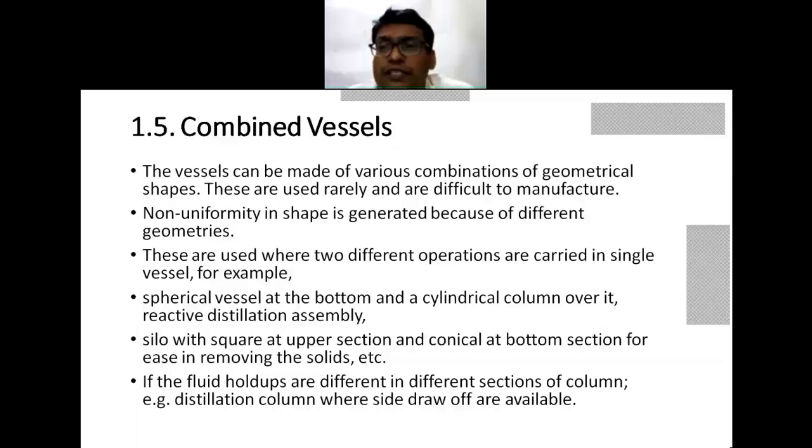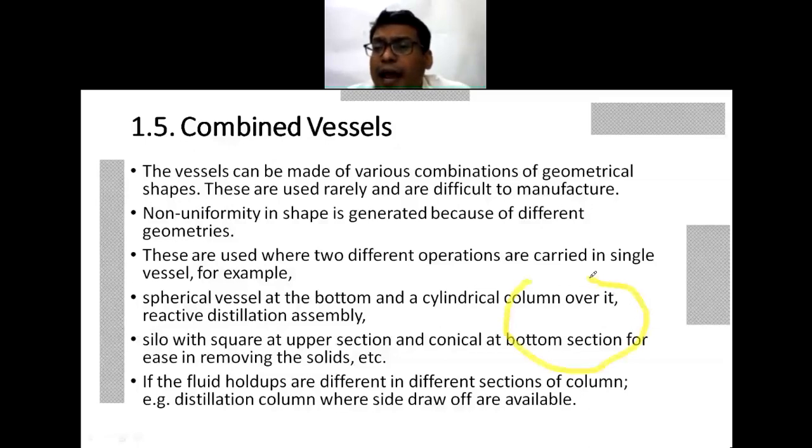If you think of a reactive distillation, at the bottom a round shape vessel will be available, where the reaction will be carried out. In the bottom section is the reactor, and in the upper section there will be a distillation column, and that is why it's a reactive distillation.